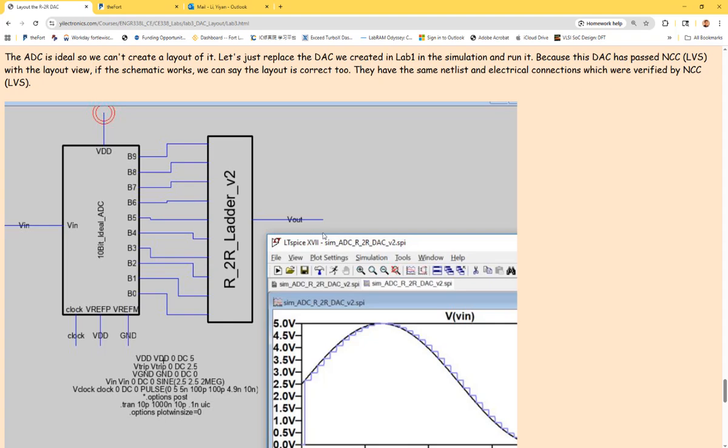Does this look good? It's not right. It's not the right way to do things. And then you find issues, you do the DRC check, you have a bunch of issues, right? So sometimes you make a good connection here, sometimes the connection here is not a good joint, and you'll see DRC issues. You see DRC issues, maybe 20, 30 or something, those resistors, still fine. What if you have 1 million resistors, 1 million components, and you do DRC, boom, you got thousands of DRC errors. Then you have to go back to the original design and manually fix every single thing.